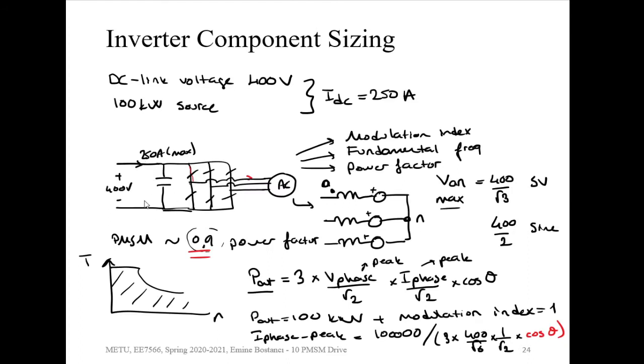This DC link is going to be connected to some other components in the vehicle too. And during the transients, this DC link can fluctuate because of the other electrical components connected to the DC link. So this DC link can change since the battery voltage may change as the SOC of the battery decreases. And this DC link may also change as the other components ask for current or send back some current to the DC link, so there can be peaks.